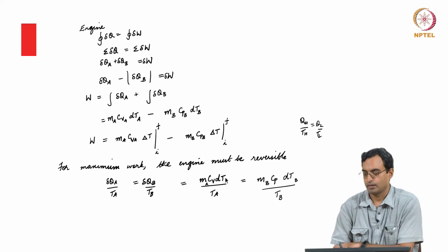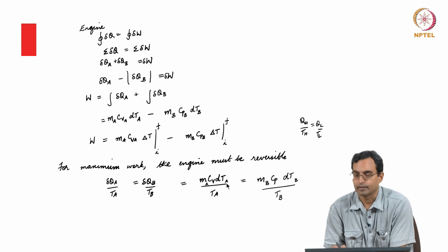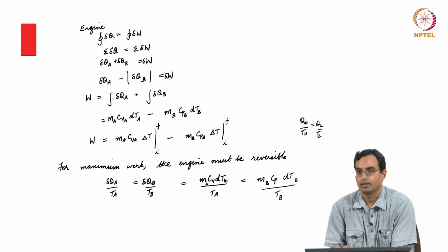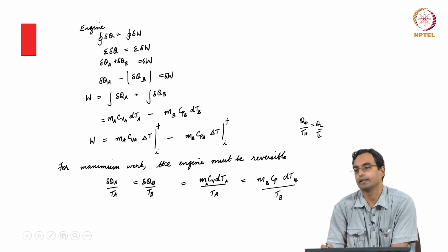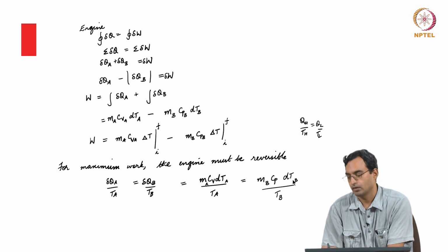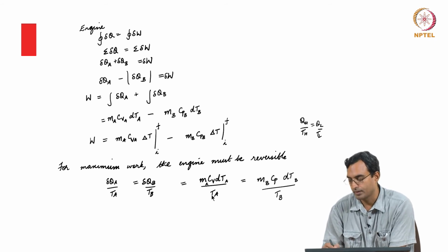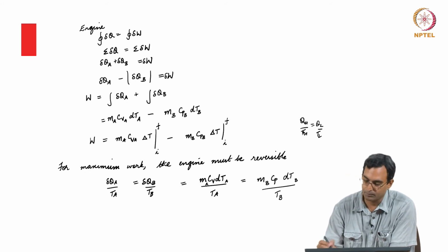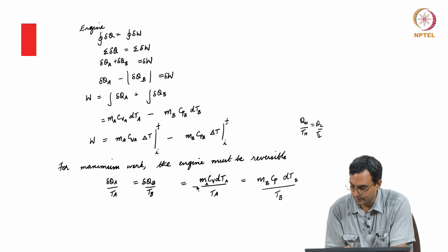So, the way this is written, the temperature of A is going to reduce. So, dT will be final temperature minus initial temperature, which will be negative. Over here, the temperature of B is going to increase because I am giving heat to the piston cylinder arrangement, so this will be positive. So, they are written in such a way that one of these terms is negative and one is positive. But when we are writing it in this form, we need both to be either positive or negative. So, let us put a sign on one of the sides. So, we get this.